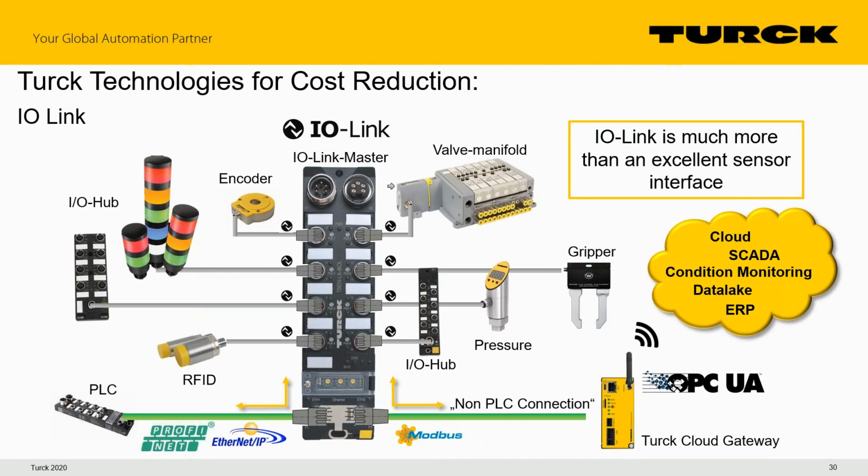We've got a valve manifold here. So most manifolds up to 16 valves, whether they're single or double acting, can be run from one IO-Link master port. And we have things like grippers, which also typically use up a little bit more I/O points than just a single point, available with a single I/O port. So, we've reduced what could have been 4 or 5 or more I/O blocks into one IO-Link master block. So it helps us save money in that way.